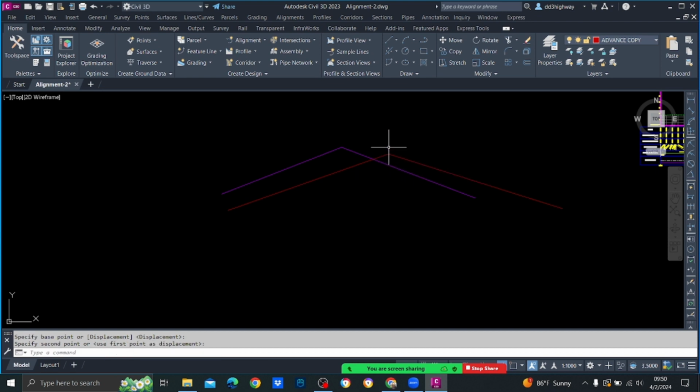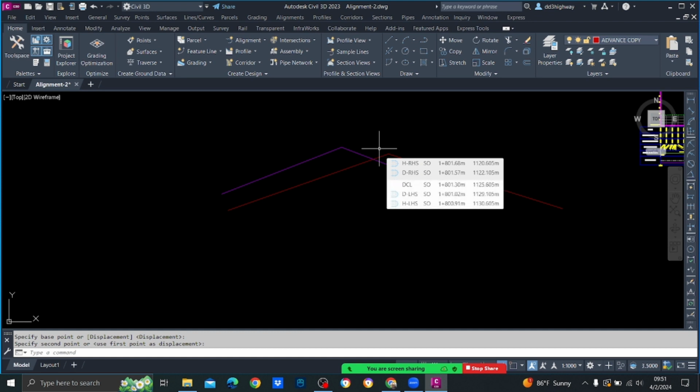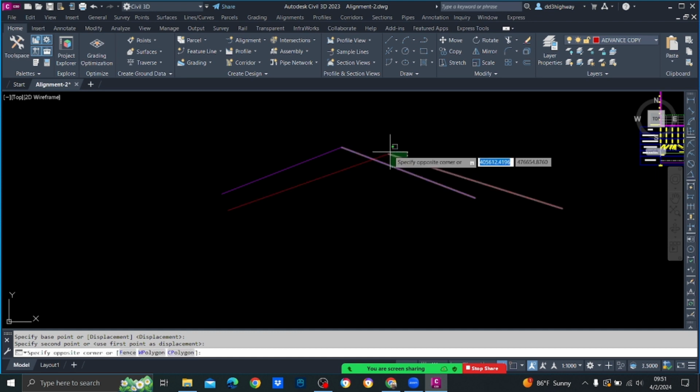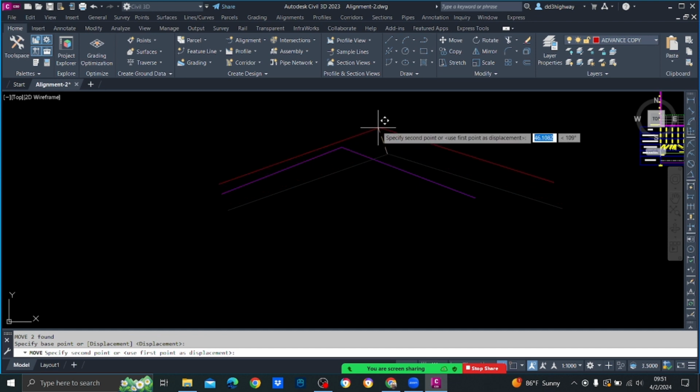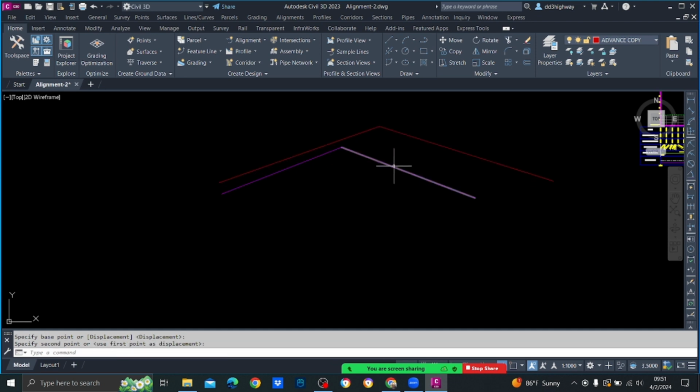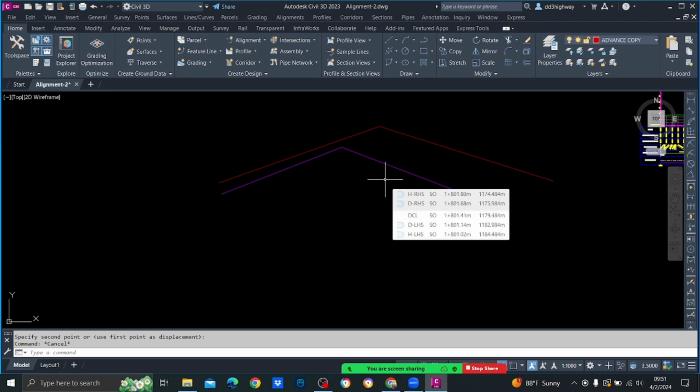Now 100 millimeters is there, but the problem is on one side you are going to cut the road. Is it necessary? It's not necessary. What you could do is set this level in such a way that a minimum 100 millimeter thickness is ensured. So here the minimum thickness is coming at this point. This is 100. Then this may be 250. Can't help. Okay. Understood. So this is what we call recambering.